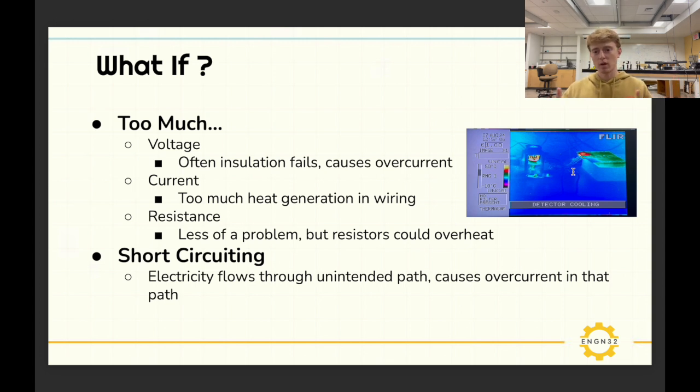Short circuiting just refers to a situation where I accidentally have some sort of electrical connection in my circuit that I don't expect. Okay? So for example, if I have a circuit board laid out that I've soldered up and I accidentally drop a wire, let's say I was cutting some wire and it just happened to connect across ground and the positive power line, now I have a short. It's probably going to melt, okay? Or cause some sparks and blow out.